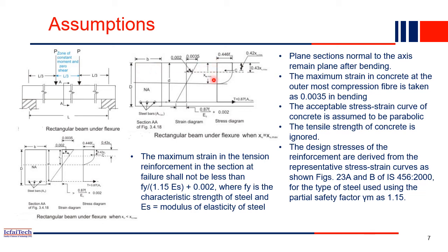So the stress strain diagram of concrete, if you recall, we have discussed IS 456, right? So this is the stress strain curve. Let me draw it here also. In IS 456, how will the stress strain curve of concrete be? Something like that, parabolic and then straight, right? If you check IS 456, this is the strain axis and this is the stress axis. So this is the parabolic part. Here the strain axis is horizontal and the stress axis is vertical.